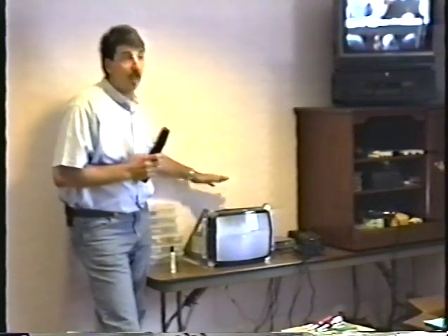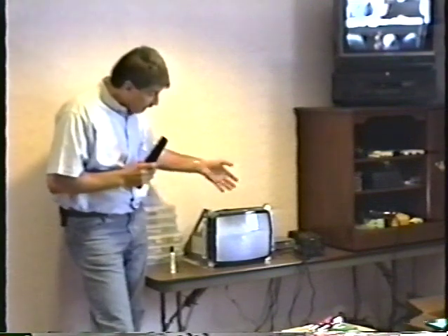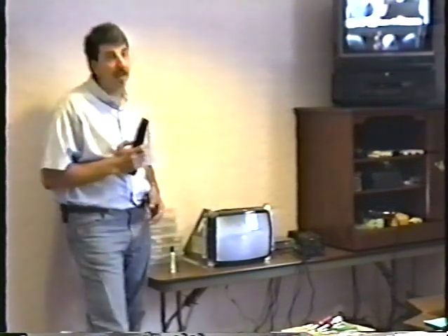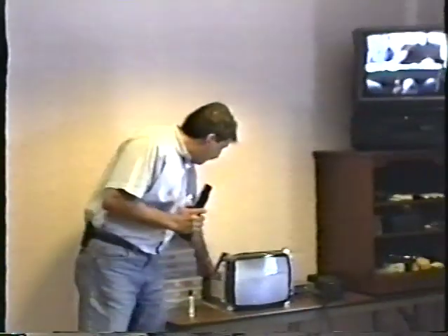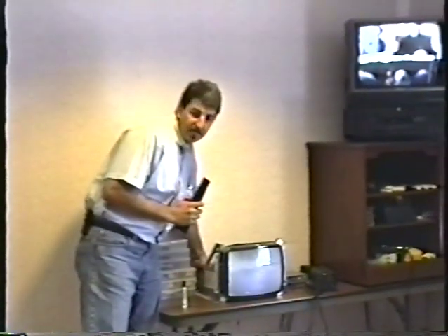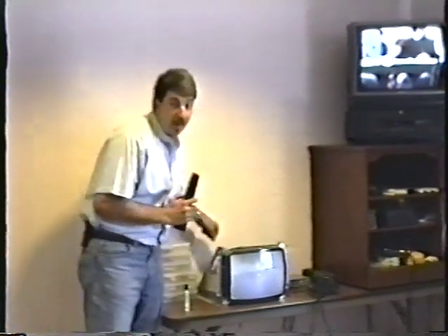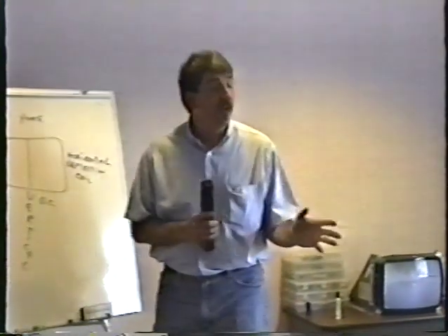Obviously, there's a power supply in the monitor. That's got to be working. If the power supply was crapped out, I wouldn't see anything at all on the front of the screen. So just by reaching back here and cranking up the brightness control, the screen control, and seeing raster, it means that a bunch of stuff in the monitor is working okay.